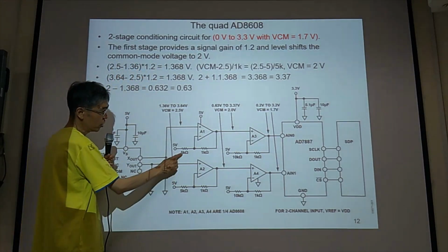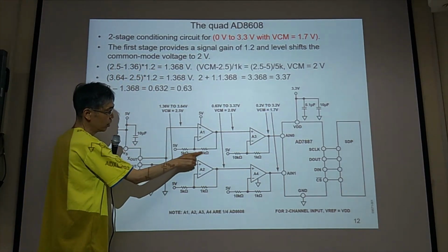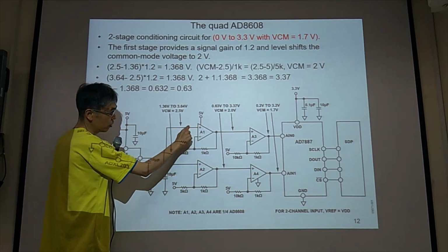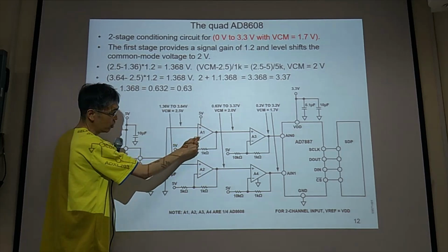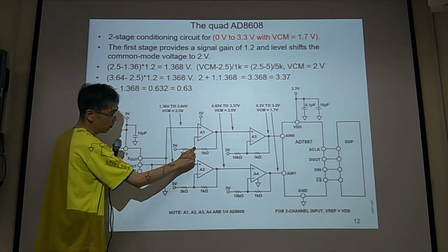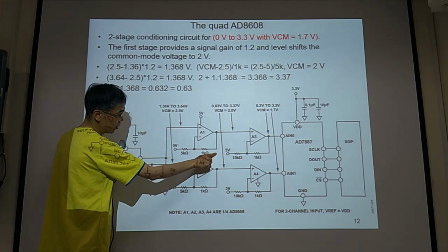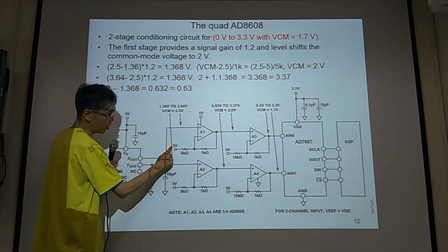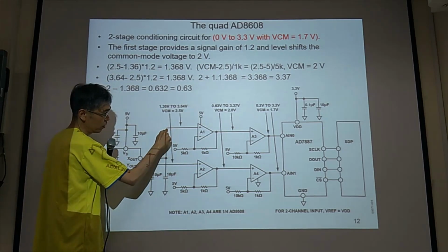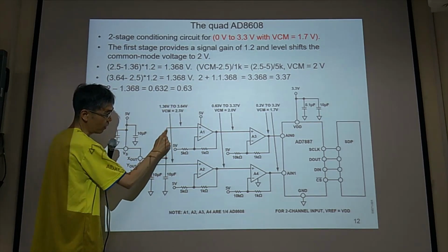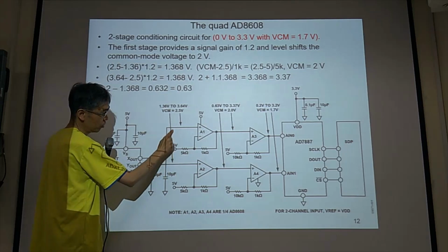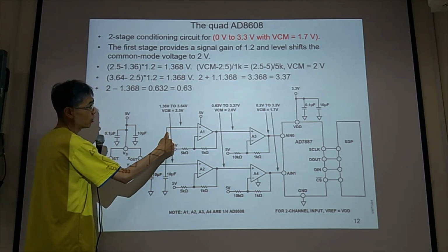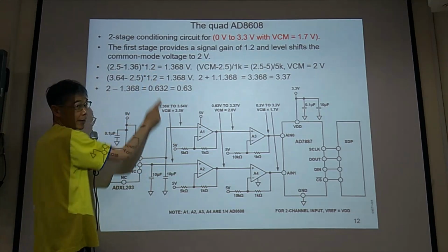So this is 5K, 1K. So for differential input, Vx in here, also Vx, and this is V out. So Vx equal to V out times 5K plus 1K, then the denominator is 5K. So 5 divided by 6. So you do reciprocal. So it's 1.2 is the gain.